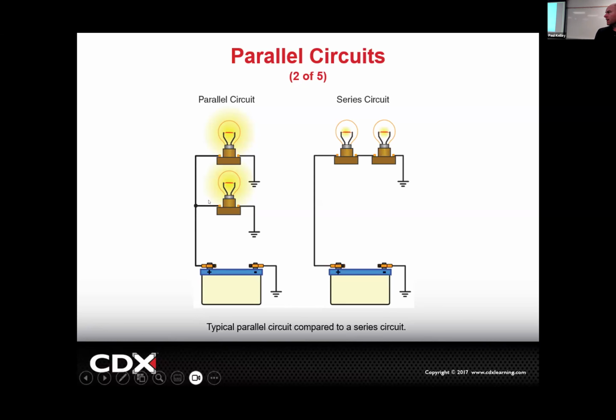No, it's the battery. Somewhere, I would suspect, I agree with you, you're following pretty well. I would suspect most likely between here and here. And why specifically here? Because the source voltage is going to both of them. Right, so if the problem was here, what would happen? This one would stop. But if they're both not working, it's probably in this part.